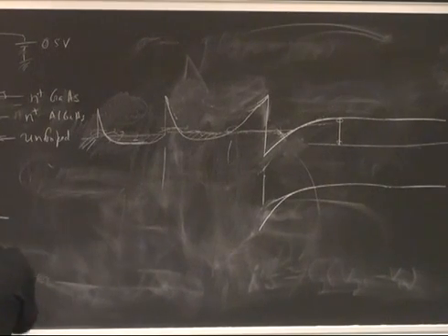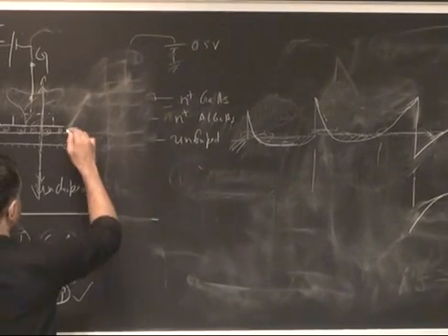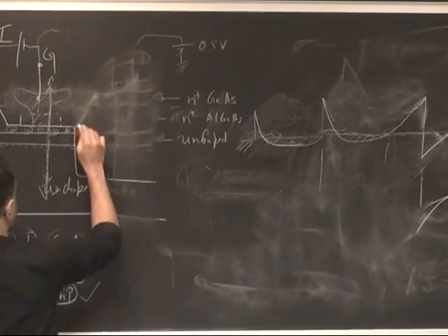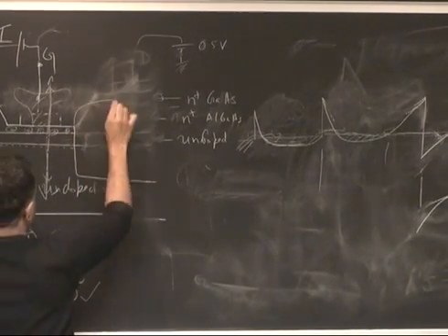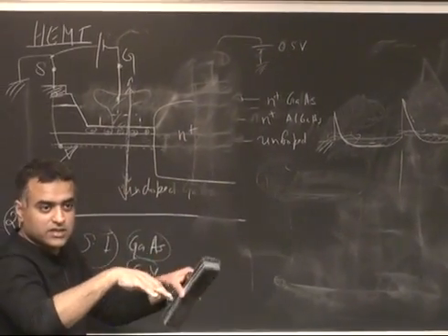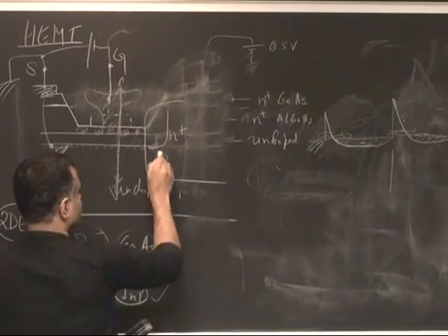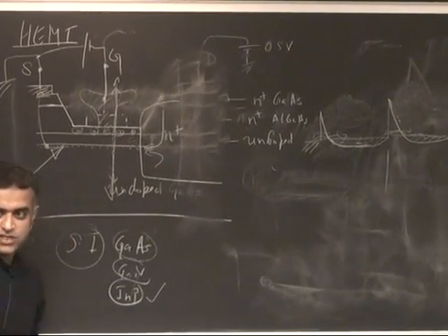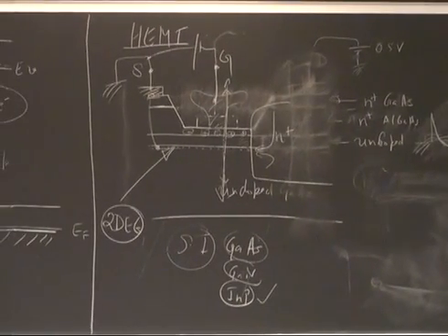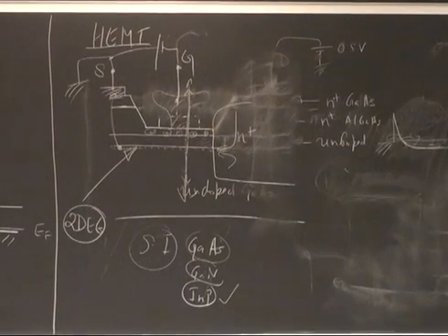Recently, in a lot of high-end devices, instead of doing multiple tunnel processes like that, after you have grown the structure you etch it down on both sides, source and drain, and regrow a heavily doped N+ region. Put it back in the MBE, mask it, and grow a lot of electrons, and they connect directly to the sides, and this gives you much lower resistance than the other. This regrown contact is more expensive because it needs extra epitaxial steps, but it gives you a boost in performance.